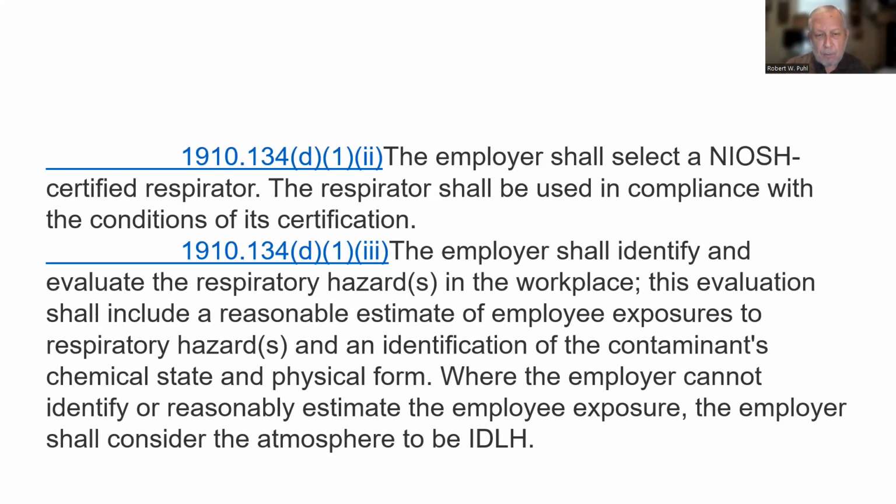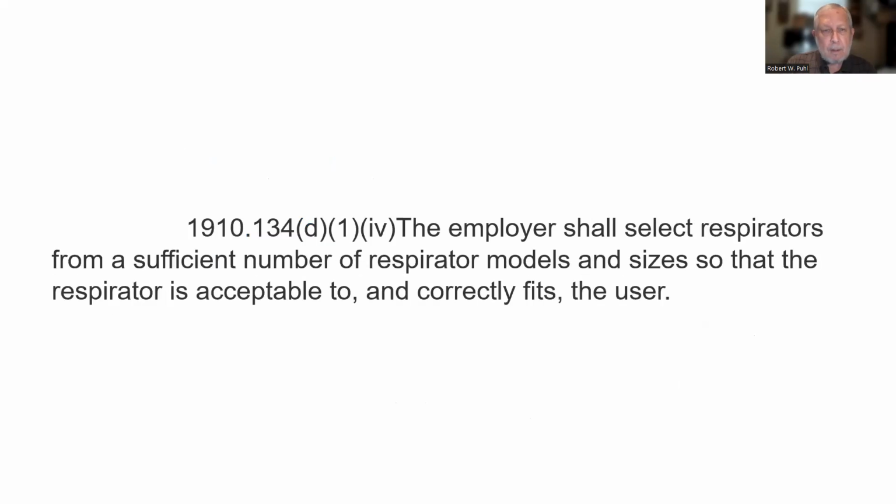In other words, is this a gas, whatever. Where the employer cannot identify or reasonably estimate the employee's exposure, the employer shall consider the atmosphere to be IDLH. So if you can't figure out what the exposure is going to be, then you have to assume it's IDLH. And that would be the worst case scenario for exposure.